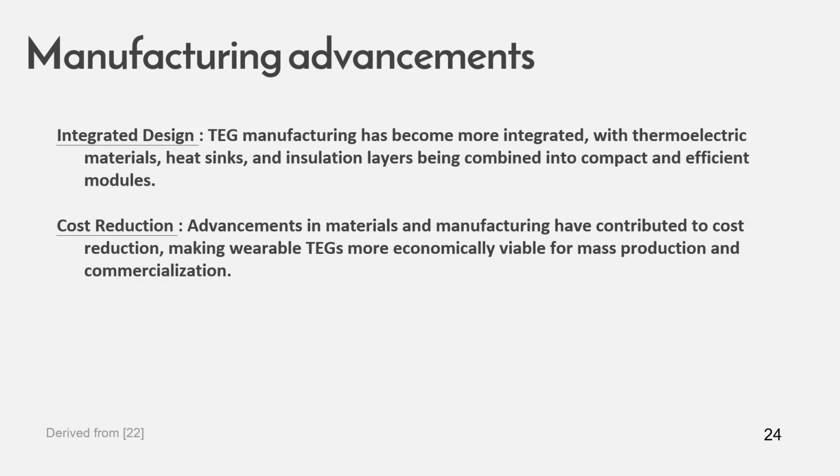And the next is integrated design. TG manufacturing has become more integrated, with the thermoelectric material, heat sinks and insulation layers being combined into compact and efficient modules. So integrated design, what it does mean is that the heat sinks and such devices are integrated directly or built directly into the TG structure rather than going for a different device or another material. The structure itself is compatible to provide heat insulation and such things inside the design structure itself.